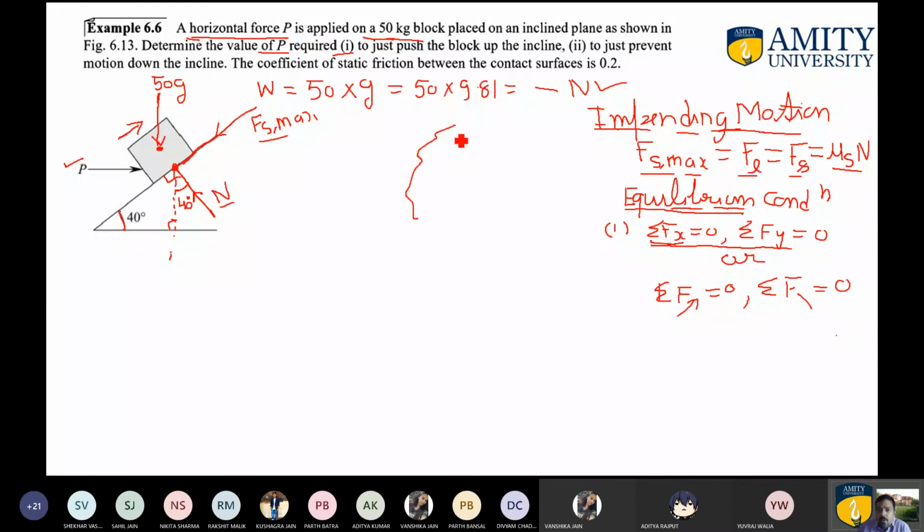From the very basic knowledge, you already know that whenever two forces which are concurrent and coplanar act over a particular body, the resultant of these two forces you can easily find with the help of the parallelogram law. What you do in a parallelogram, just draw the line parallel to the first force from the second one, and from the second, draw the line parallel to the first one. So this is how the parallelogram is drawn. Now the diagonal passing through the point of concurrency, which is this one, will give you the value of the resultant. So it is very clear, the resultant will lie somewhere in between these two forces, governed by this particular direction alpha.